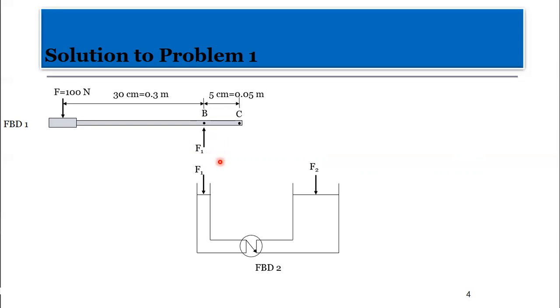But to make things more clear, let's see here. Over here, we need to obtain the area for the smaller section, which is A1, and we know the diameter to be 1.5 centimeters. So if we convert everything to meters, we have 0.015 meters, and knowing A1 is a cylindrical slot, it's going to be pi d squared on 4.